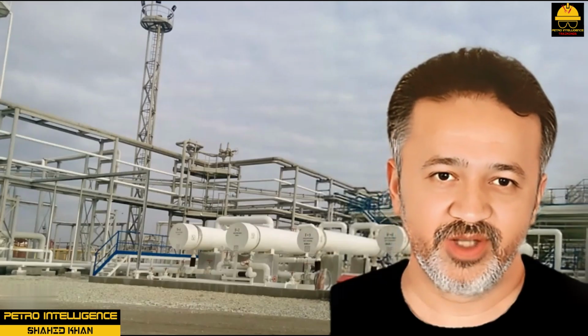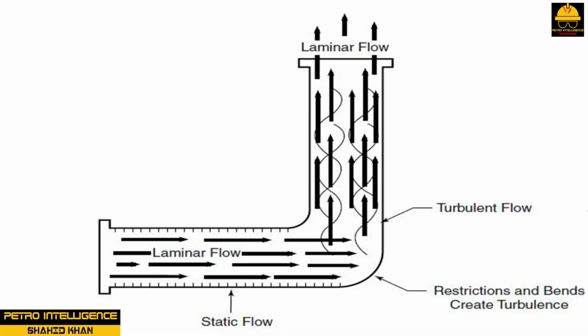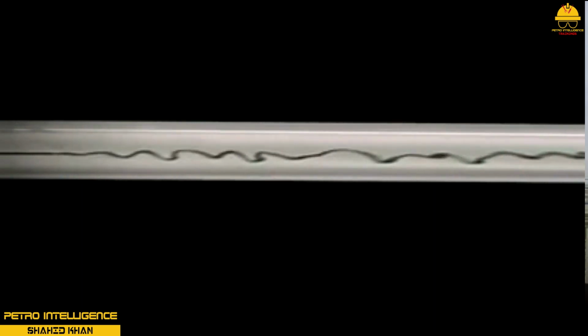Laminar and turbulent flow. Two major classifications of fluid flow are laminar and turbulent, as shown in the picture. Laminar or streamline flow moves through a system in thin cylindrical layers of liquid flowing in parallel fashion. This type of flow will have little, if any, turbulence, swirling or eddying in it. Laminar flow usually exists at low flow rates. As flow rates increase, the laminar flow pattern changes into a turbulent flow pattern.